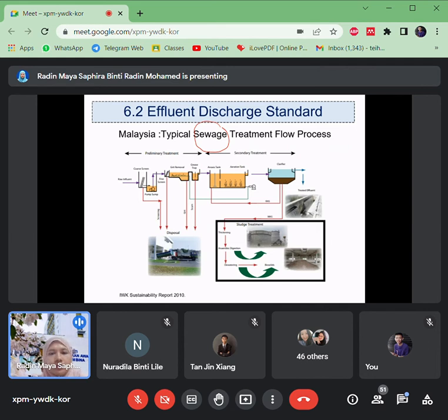We have aeration to improve the water. Then the next process is the biological process, which is the clarifier. Ini yang kita actually menggunakan our microorganisms, good bugs, to do the biodegradation of organic matter. The brown color is the sludge formation, sisa lah. The sludge will be managed by thickening, or we produce biogas from the anaerobic digester, or we produce sludge cake by dewatering it.